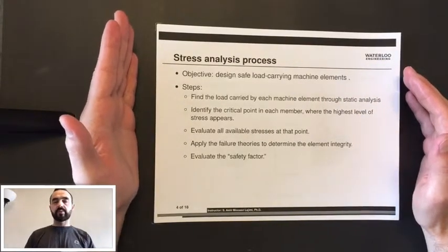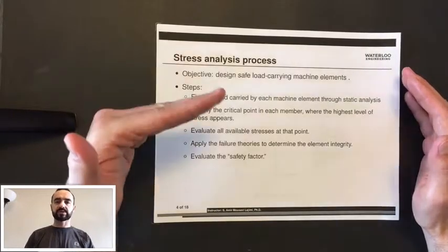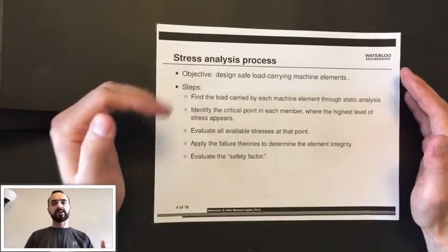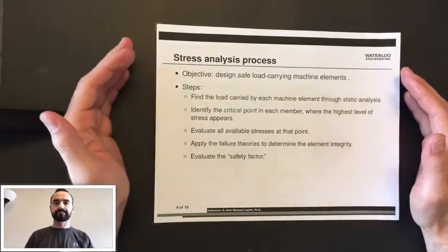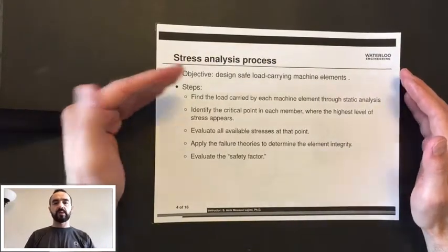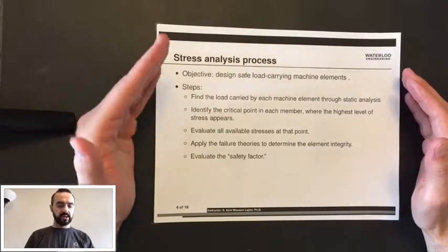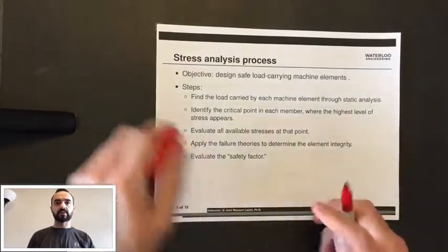The first step is to find the loads carried by each machine element. Once we've done that, we identify the critical point in each member. And once we identify the critical point, we evaluate the stresses at that point, and then we apply failure criteria,